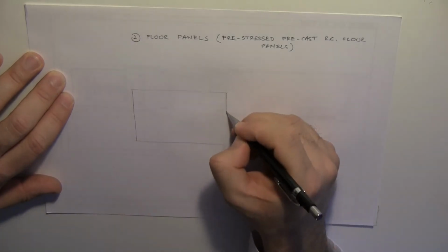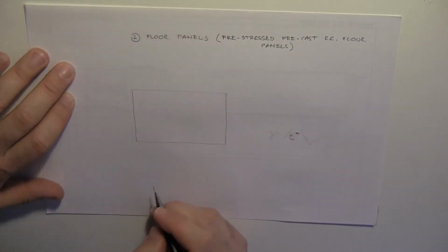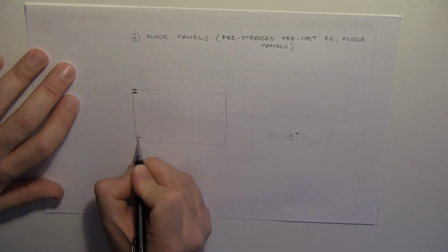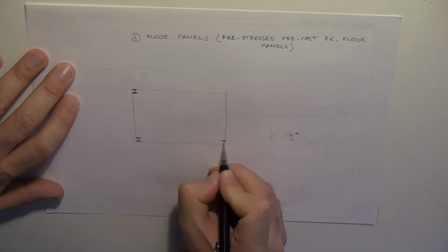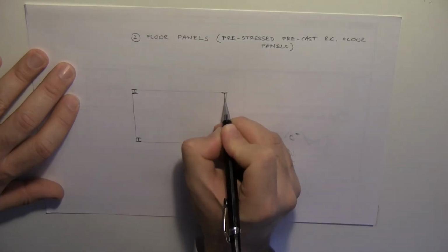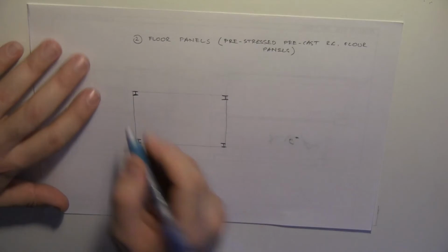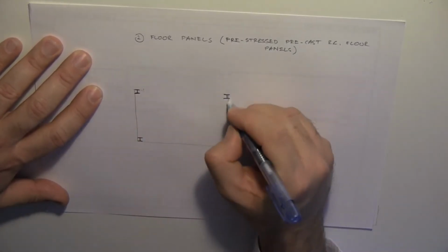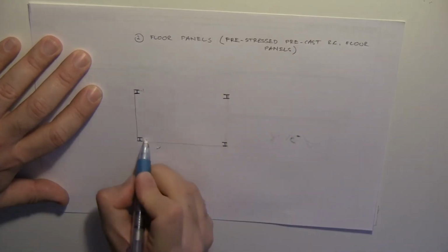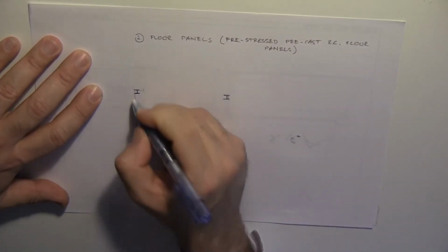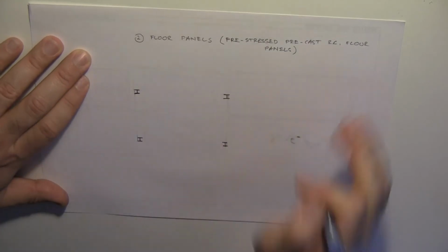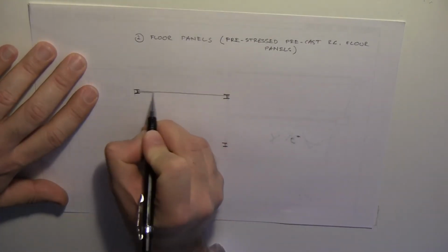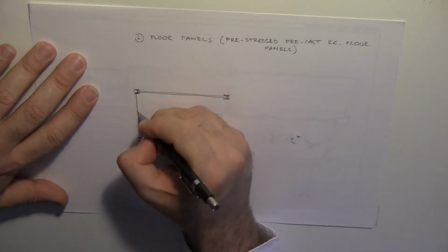We are going to draw our floor again, borders of floor. Again, we are going to have our edge profiles. Once we draw the edge profiles, let's erase the borders, because you know that the beam profiles are going to be placed center to them.